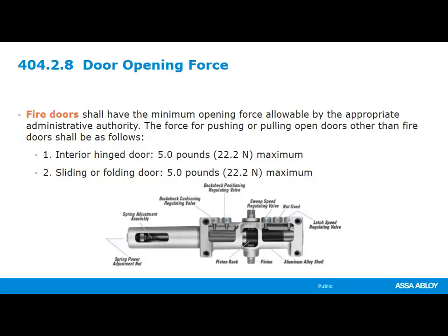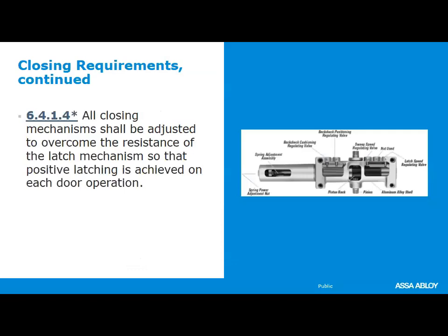Proper installation of your door closers is critical in order to get the full benefit of your spring power adjustment, as well as the sweep and latch speed. And this is what it says in NFPA 80, which is the standard for fire doors and other opening protectives.